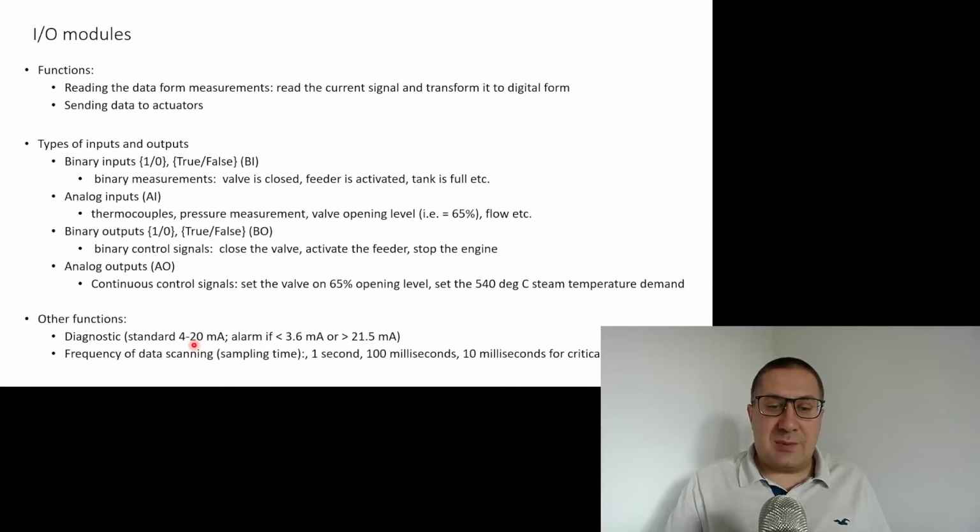What is the sampling time? Usually it's 1 second or 100 milliseconds, but sometimes for critical measurements it's 10 milliseconds. Usually the higher frequencies are not possible. If you would like to measure vibrations, I don't know, on the turbine or something like this, you will have to have a dedicated system for this.